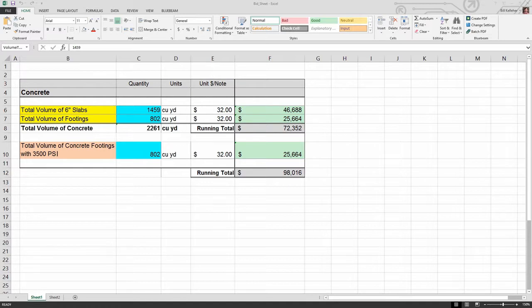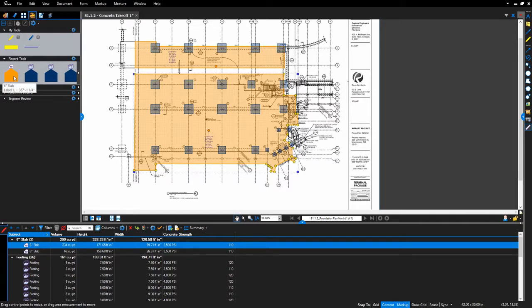Quantity Link is only able to create links if there is already existing markups with that data in the source PDF. The best practice would be to create toolsets with all the specific markup data preset up, such as the subject line of the particular material you are including on the bid, and any additional custom choice or custom text information, such as the PSI strength we just looked at. You would then perform the takeoffs using the toolset on the PDF, and then open up the Excel file and create the links as your final process.